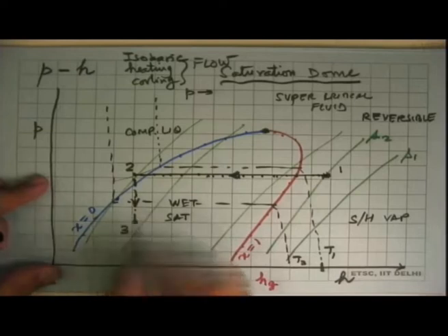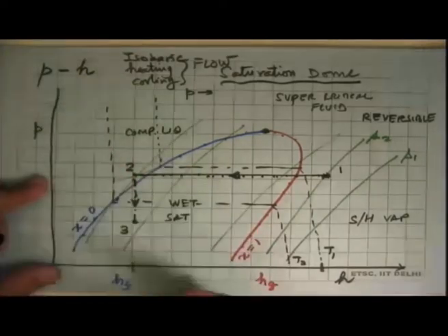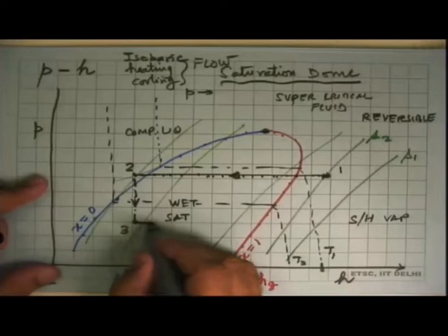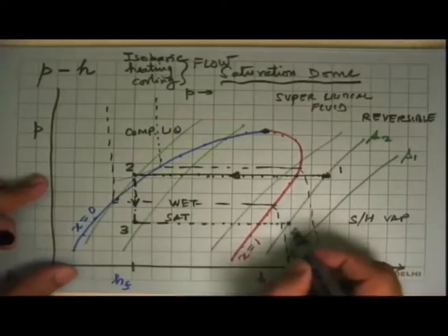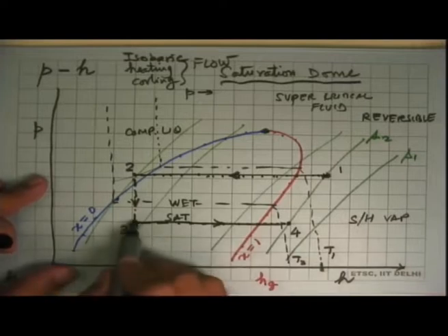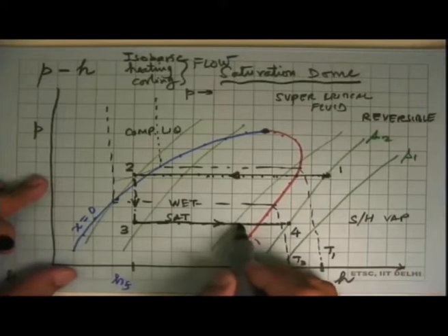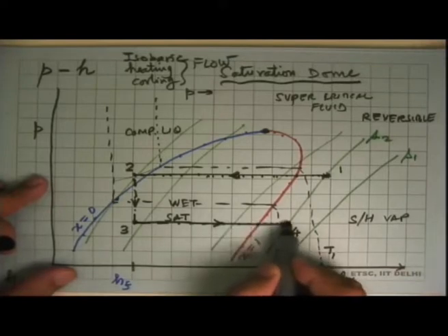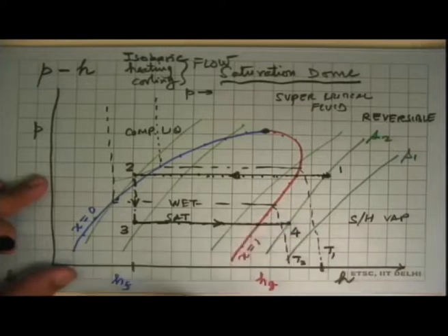It is at this state that the refrigerant enters the evaporator where the cooling takes place and keeps getting heated up, and it goes through a bunch of effect in the room, and the wet saturated refrigerant kept getting heated, its dryness fraction kept increasing, became x equal to 1, and then became a superheated vapor there. That's what was happening.